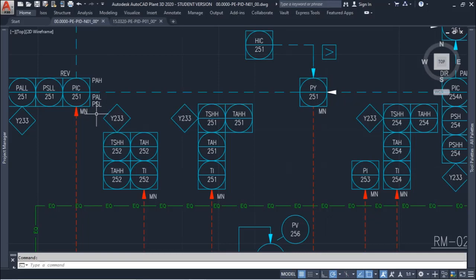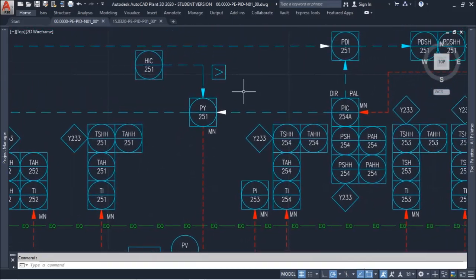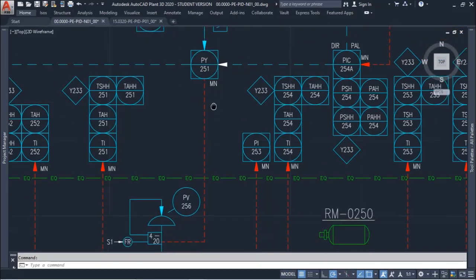That means that some action should be taken if the set point for this is reached, and it sends the signal to a PY that needs to choose the higher one from these 3 signals. This is the symbol for higher, so the signal that is higher is what will be selected to be sent to the recirculation valve.